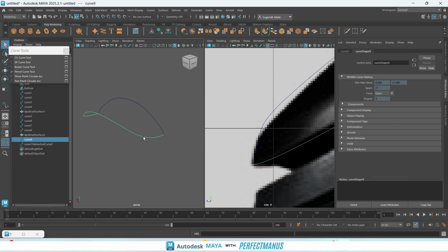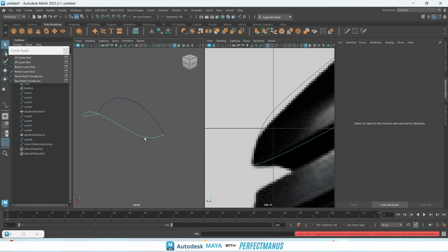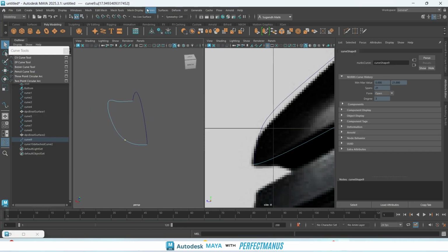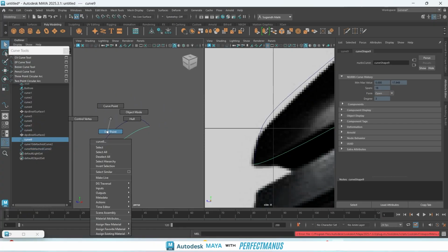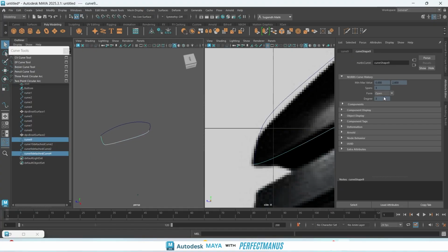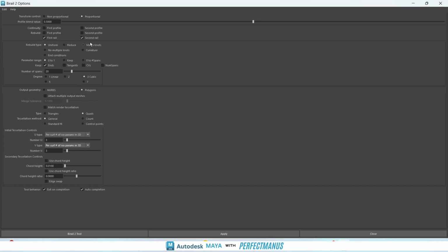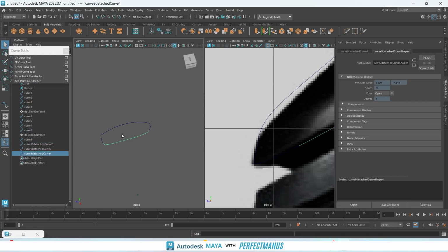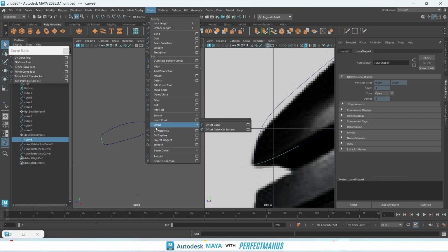Now you can put those cuts by going the curve point, press on that cut. Your curves detach. Similarly for this part, curve point, curves, detach. So you got this one with 3 spans, you got this one with 4 spans. So here either you increase this spans or this one, because in this setting you only work on rails. Your rail ones, this is rail, this is rail, but these are not rail, so you need to change the spans separately.